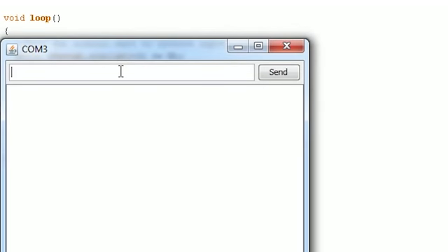So we have our Arduino plugged in via USB on the other end. There's nothing connected to it, just the Arduino. We just want to test the serial functionality. So if we send it a 1, we should get a 1 back. What? A 49? Oh, that's weird. What happens if we send a 0? 48. Huh. That's peculiar.